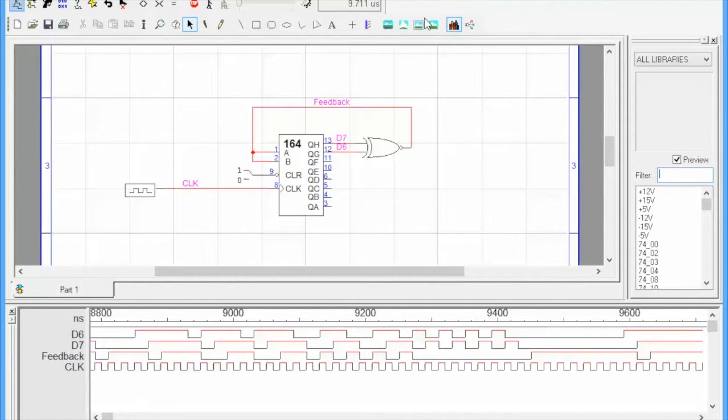So let's make some meaningful changes to this circuit. Let's delete that feedback section once more, and then we're going to go over here and look for an open collector buffer. So we just type in buffer, and the one I want is this buffer here, open collector, and I'll double click on it. Now what about rotating it when it's being dragged from the parts palette? Well, you can use the arrow keys. So if I hit the left arrow key, I'll get it in the opposite direction.